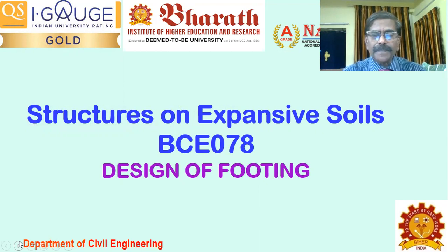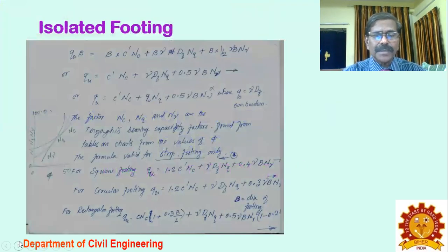What is a foundation? Foundation is that part of the structure which will generally be located below the ground level or the water level as the case may be, which will transfer all the loads onto the underlying soil at a tolerable stress level. The tolerable stress level may be a net safe bearing capacity, or ultimate bearing capacity divided by a factor of safety, or safe bearing capacity and so on. So we are talking about the design of footing, and footing we call the foundation.